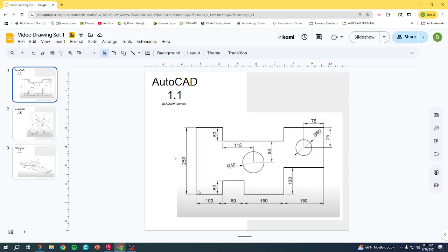What you have to do is look over at the overall height using one of the dimensions on one side. In this case, 250 minus 100 gives you 150 left. And then this 150 here is the same as the 150 up there. You add 150 and 80 here to get the length of this line, which is 230. Or you can see that this is halfway and it's 115, which you can double, and that's 230.